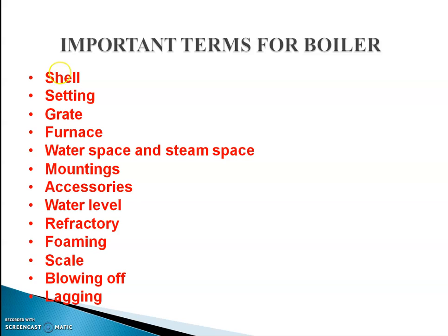The setting is very important for the boiler. For the hot flue gases and for better combustion, the setting is very important. The primary function of the setting is to conserve heat in the boiler and form a passage for the gases. It is made up of refractory bricks forming the furnace wall and a combustion chamber. It also provides support for some types of boilers.